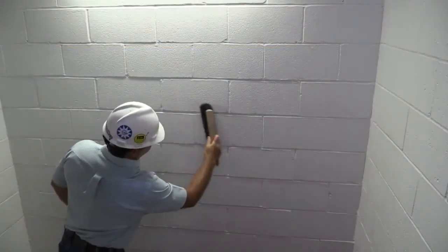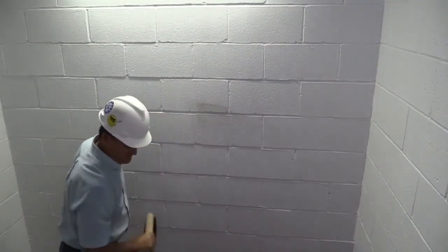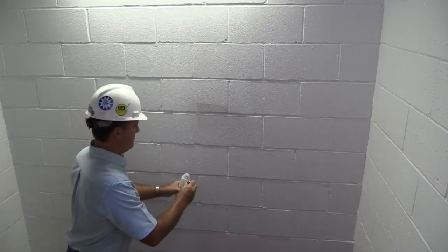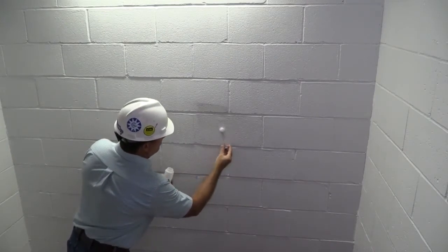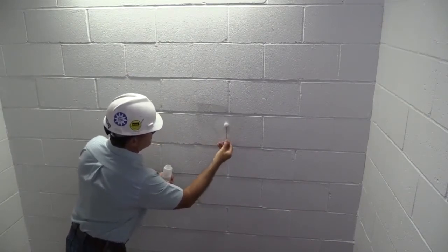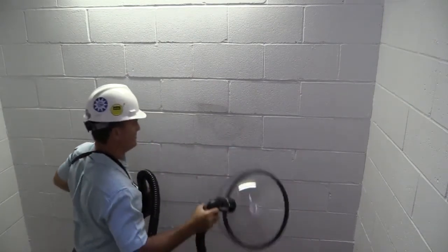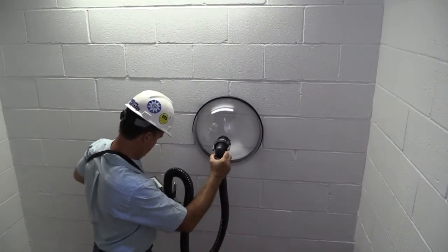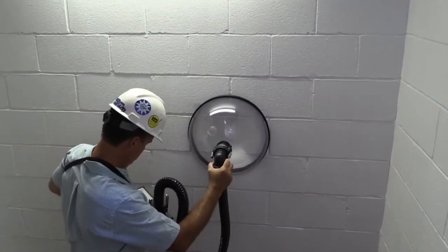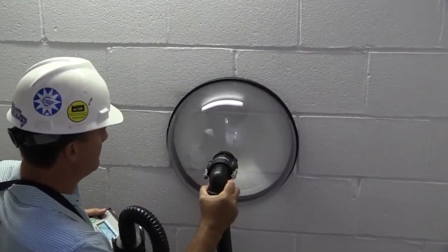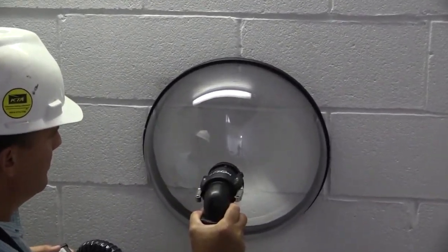To run the test, first, clean the test area of dirt, dust, and debris. You should also make sure the surface is not too hot from torching, or frosted, or extremely wet when you run the test. Apply a thin film of the solution over the test area, but don't apply it too heavily, otherwise the solution could froth and foam. Once the solution's in place, hold the dome firmly to the surface. You don't have to push too tight to create a perfect seal because the fan will make up for the difference. But then push the green button once to activate the unit and a second time to start the fan.